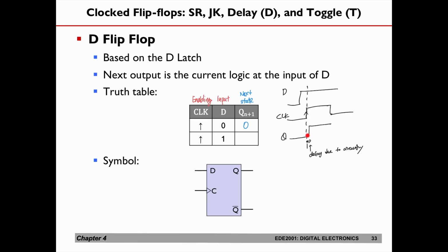In the previous timing diagram, we reduced this to 0 to simplify things. But in actual fact, there will be a small time delay, and that small delay becomes very sensitive when your clock signal frequency is very high. When the frequency is very high, the period is short, and the propagation delay might interfere and cause some synchronization issues.